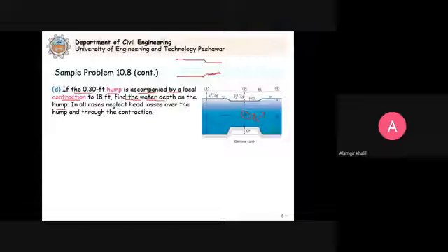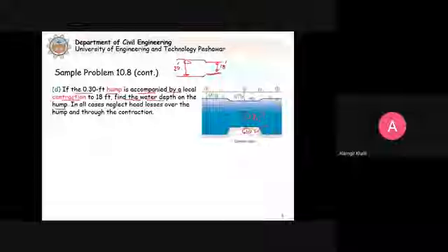The channel width is reduced, and it is combined with this hump also. At this point we have the hump also. So the width of the channel is 20 feet, and here at the hump, the channel is reduced to 18 feet. So now at the hump, we have delta Z and also there is a contraction. So we are now combining the two. So the question is, because of this, what is the depth of flow? What is this Y2? Clear? So neglect the losses. This is what we have done in all the cases.